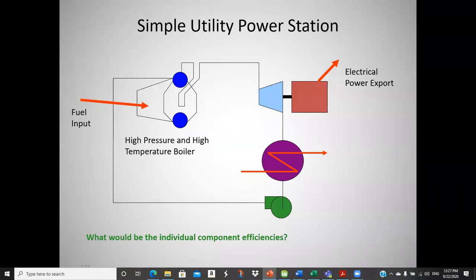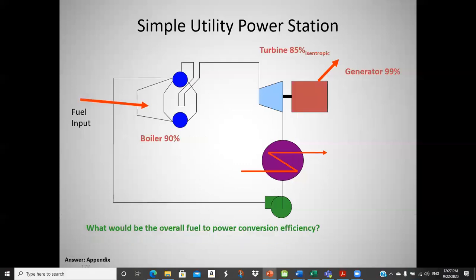Okay. So if you look at individual component efficiencies at, say, a coal power plant, what would they be? Well, these TVA boilers are like 100, 120 feet high. They're like 5, 6 stories. And they got every component, every whiz thing imaginable. So they get 90% efficient. Because it makes sense, because they put so much energy through there. It's a good investment to buy all of the extra little things, economize, recover heat and all that sort of thing.